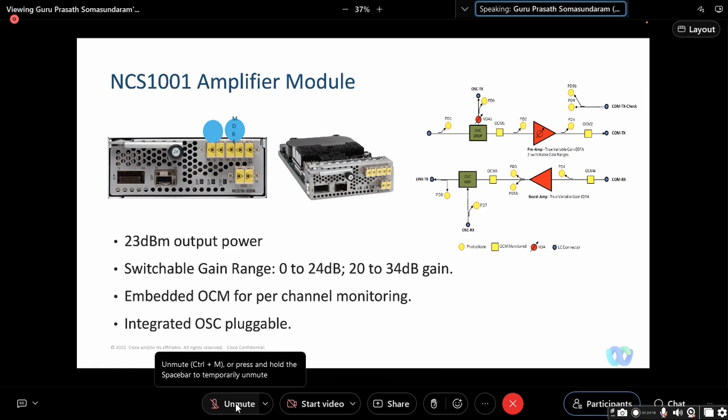Is there no provision to set an output power, with the gain varying accordingly to achieve that output power? Yes, you can do that. The amplifier can operate in two different modes. Either you configure the gain, and whatever power is received, it will just apply that gain, or you configure the target output power, which is called automatic mode, and whichever power is received, it will try to change the gain to achieve that target output power.